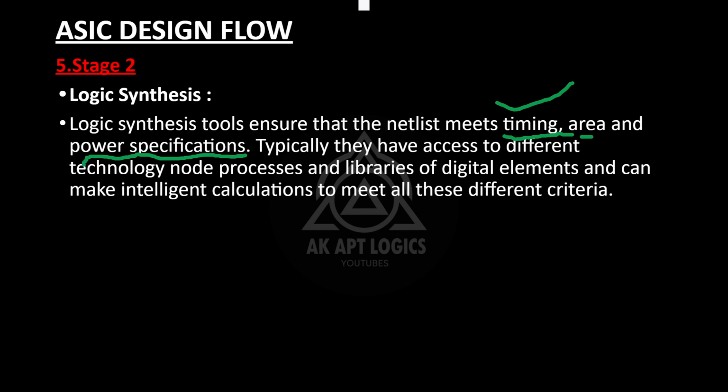The user here is not us, it is the client, meaning the product based company or service based company or the person who gave the deal or the project to the company. They give the timing, area, and power specifications. After converting the design into the gate level netlist using the logical synthesis tool, they have to check those timing, area, and power specifications.